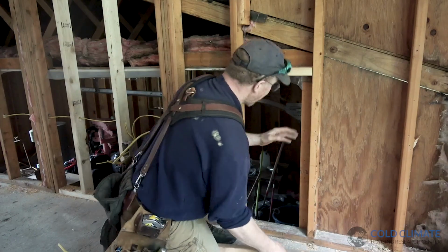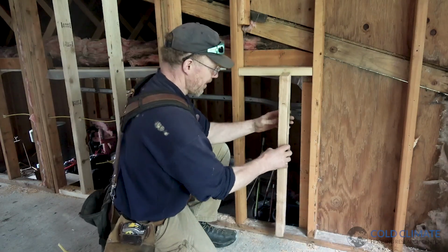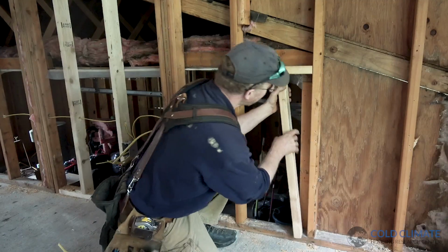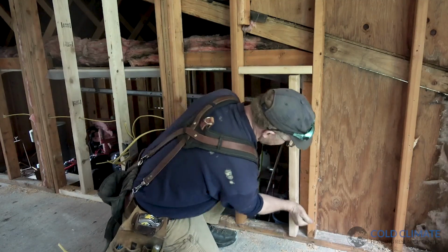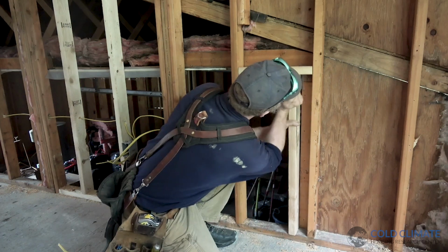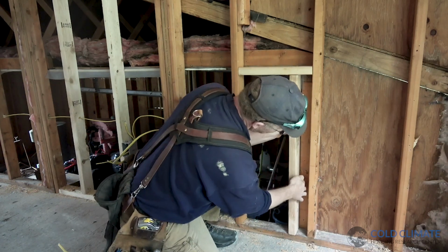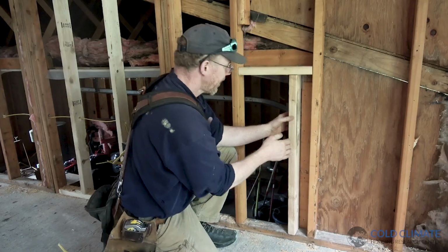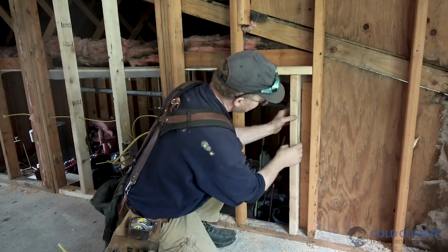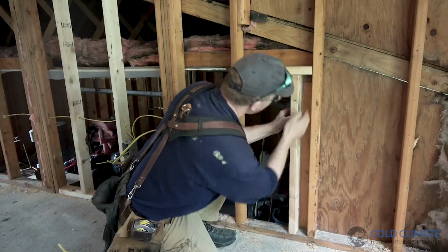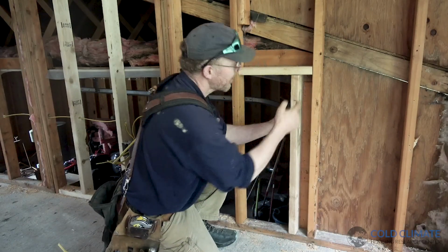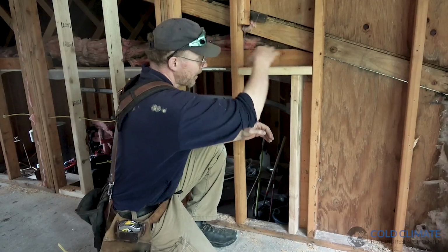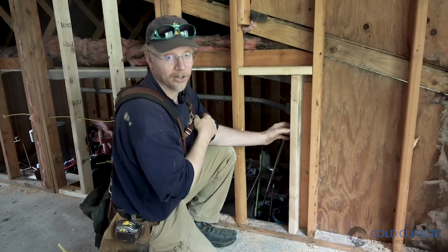Moving ahead, as I transition here, I've got a hole pre-drilled for a wire that's going to go through here and get caulked, but I'm doing the same thing. I'm installing my transition blocking here so that I'm just at the edge of the garage wall, and this will all get caulked. I'm just going to catch it here and here. This will all get caulked inside here, followed by spray foam. So we've got a belt and suspenders approach to being able to air seal this entire transition.